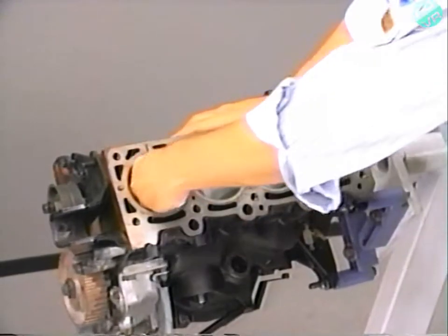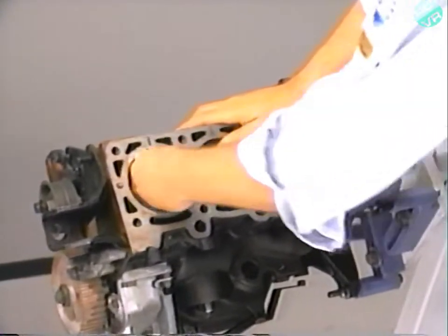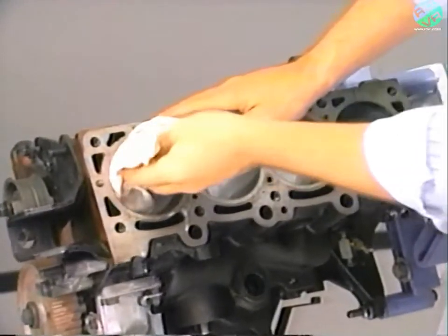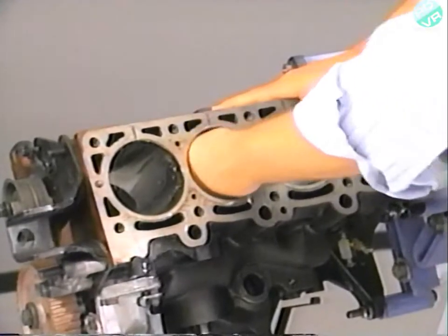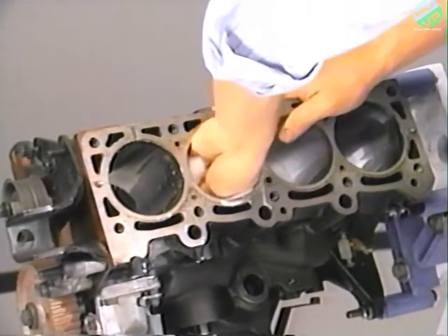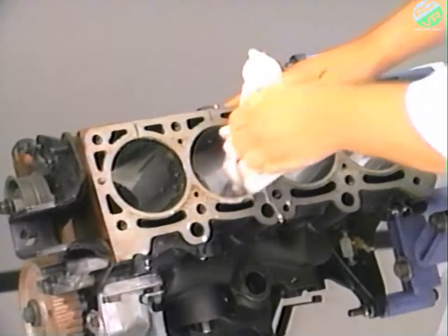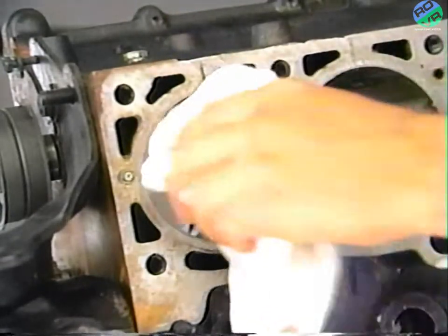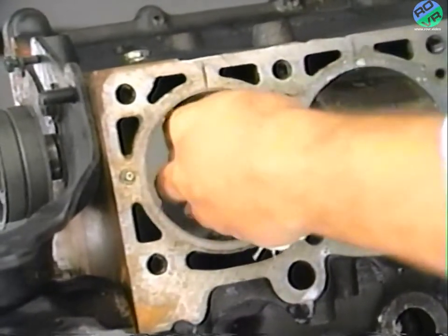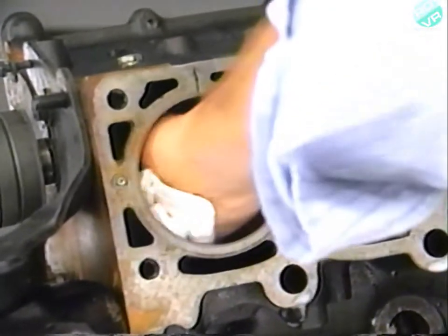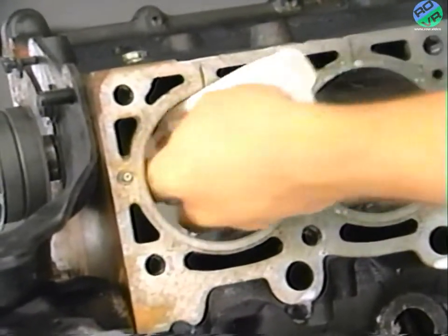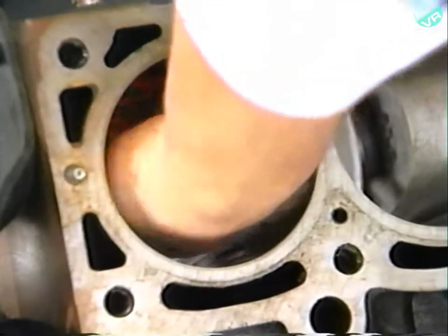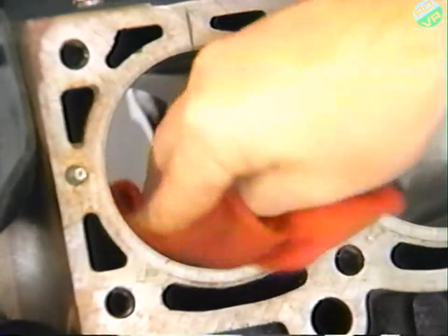The cylinder block should be prepared by washing the bore and crank journals with warm soapy water and then rinsing. This step is very important and shouldn't be ignored. Failure to clean the cylinders properly will cause rapid engine wear from the moment the engine is started again. Thoroughly dry the area with compressed air, and then check the cylinder for residue by wiping with a clean rag. If the rag picks up dark smudges, you'll have to re-clean the cylinder. After the cylinder has been thoroughly cleaned, lubricate the bore with SAE 30-weight oil.